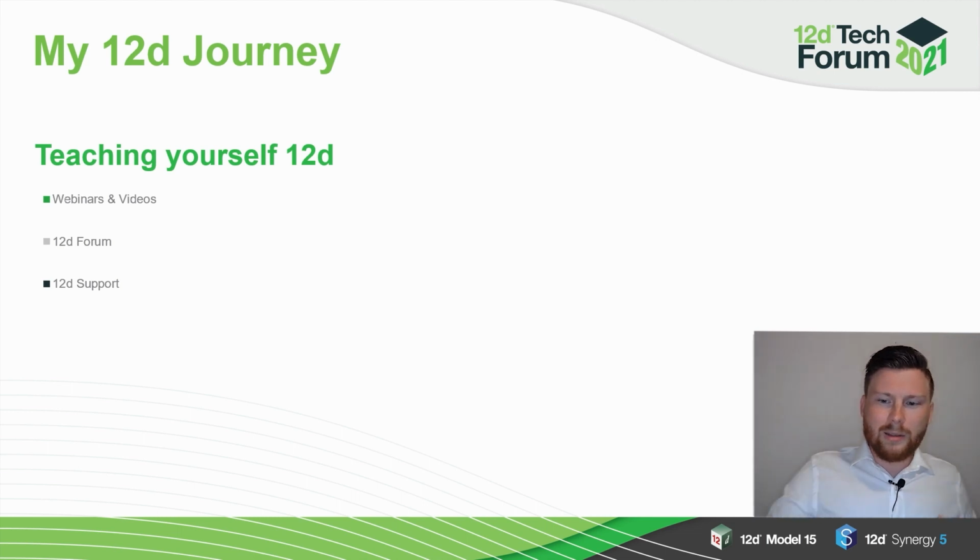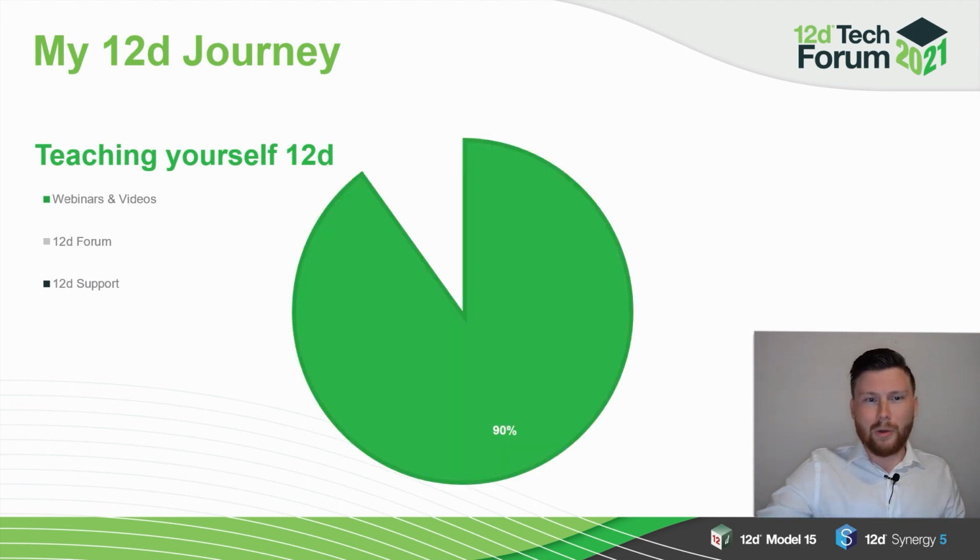As I was alluding to, I found that those webinars or videos normally answered about 90% of my questions. There are webinars on earthworks, on road design, on stormwater design. They cover off the basics: how to bring in IFD data, how to set up your super alignments, do your geometry. That was super helpful. That helped me set up all my projects.